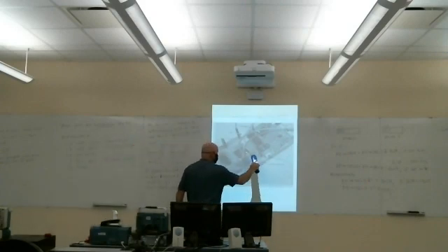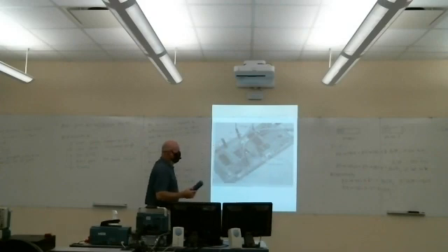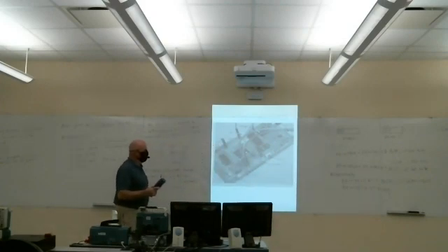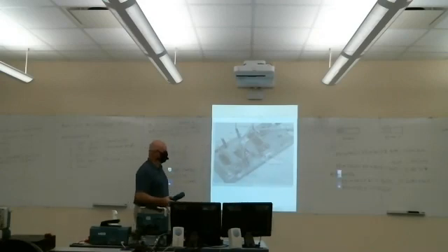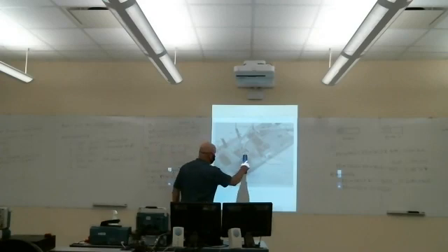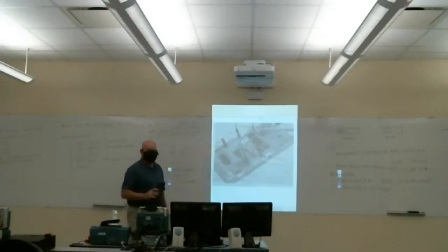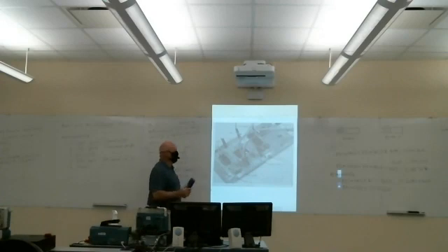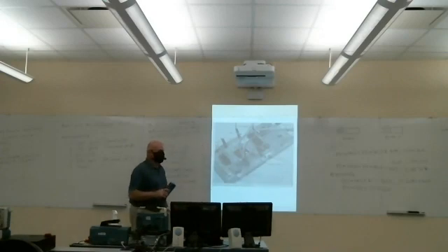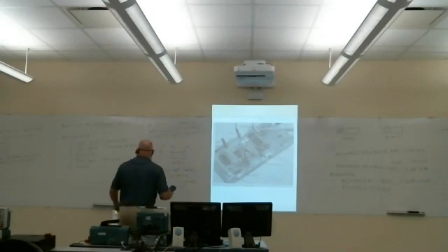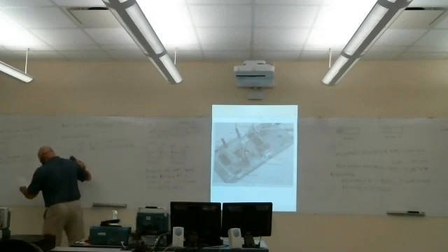Okay, these connectors are through printed circuit board traces connected to these pins on our microcontroller. Okay, but fortunately we don't have to try to attach wires directly to the pins on the microcontroller. That would be really tough. Instead, we'll connect wires to these connectors to get access to those pins.